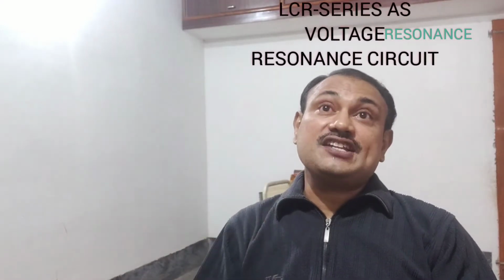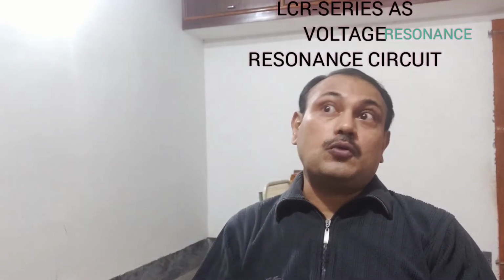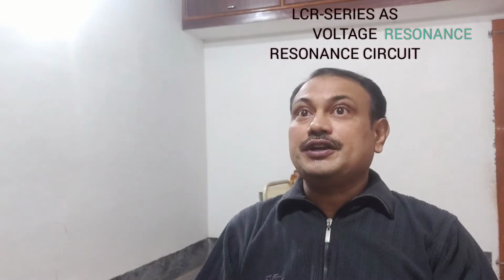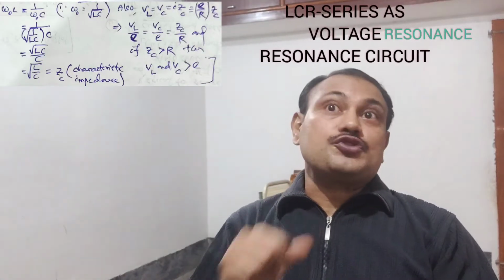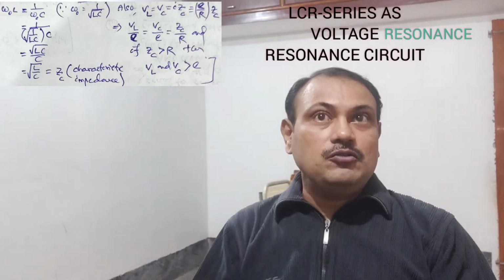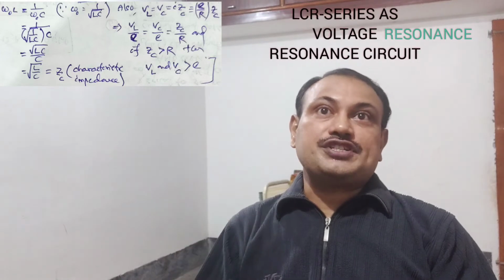Now, LCR series resonance is also called voltage resonance because at resonant frequency, the voltage across the reactive components of the circuit becomes extremely high, up to a dangerous level even, over the source voltage. That often causes breakdown of the induction coil or even the capacitor insulation, which can be proved as follows.